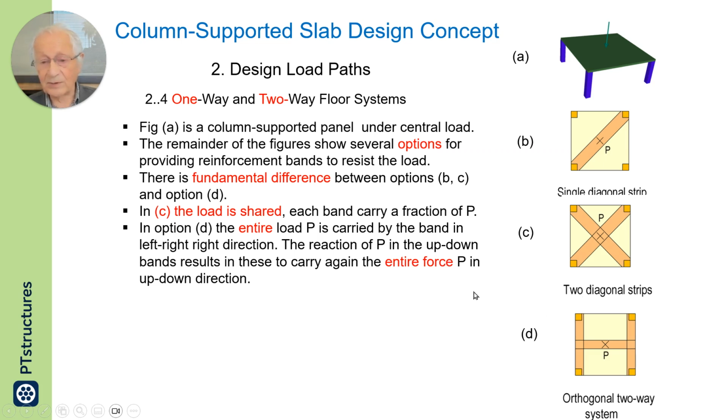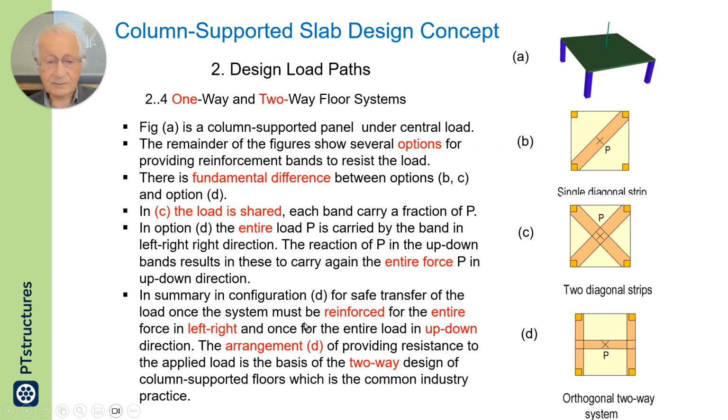So I want to emphasize the word entire. Entire in left-right, entire in up-down. That is where it leads to the design of column-supported floors in two times, once for the entire load in one direction and once for the entire load in the other direction, because this is the model used.